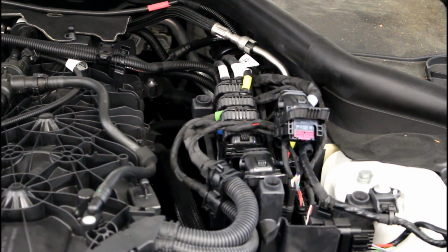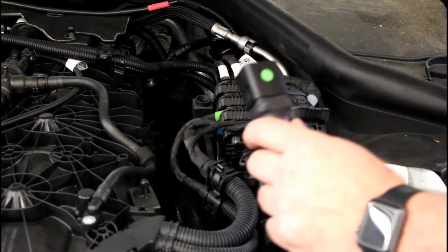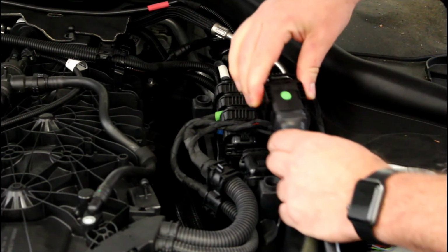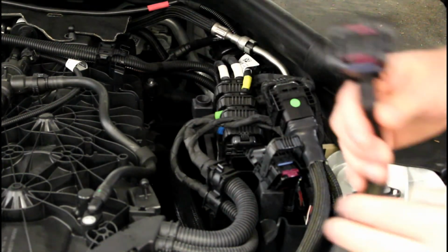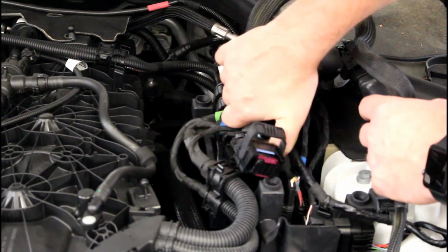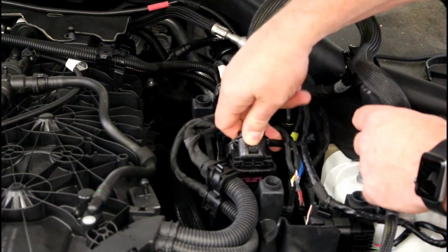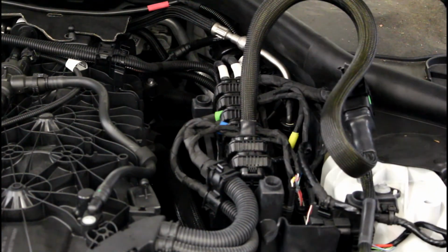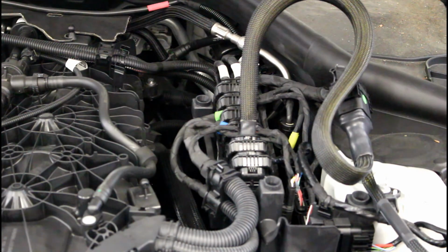Okay, so let's hook it up to the DME or engine ECU. It's meant to be a piggyback type connection that's going to connect to the actual engine ECU wiring and then hook straight up to the DME or engine ECU. This will be a way that we can actually see power and ground coming from the ECU. Plug back in the connector number 1 and we should be good to go. This side is going to go into our pinout box or breakout box.